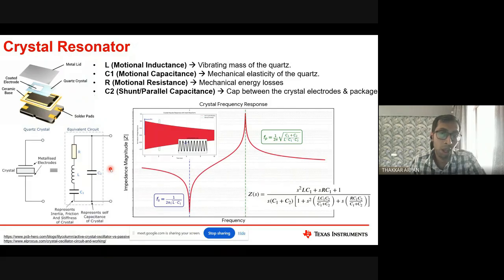So you have to ensure that the extra capacitance you are putting is not more than that. So it has a certain restriction. Basically what I'm trying to say is you cannot move this frequency a lot. In fact, you cannot increase it in any way, until and unless you change the temperature itself, when that changes C1 and C2 itself, right?